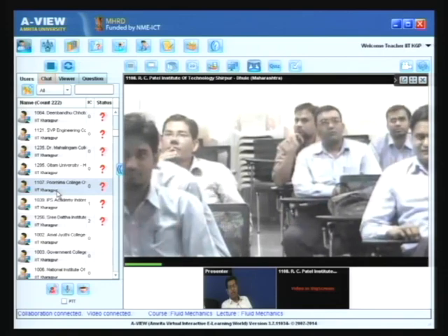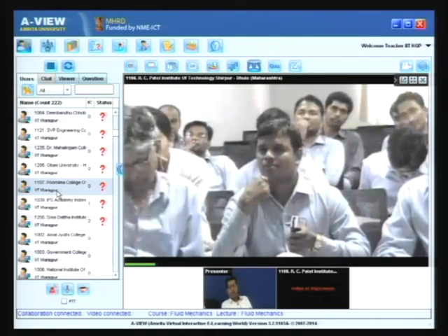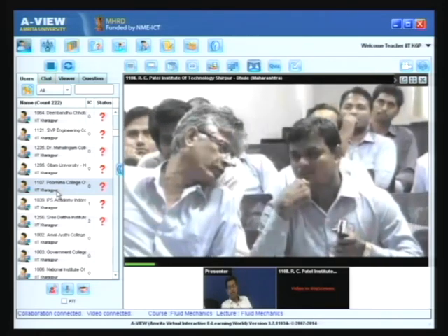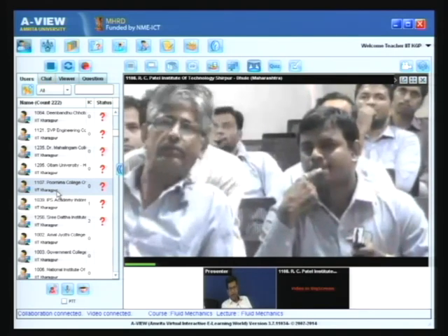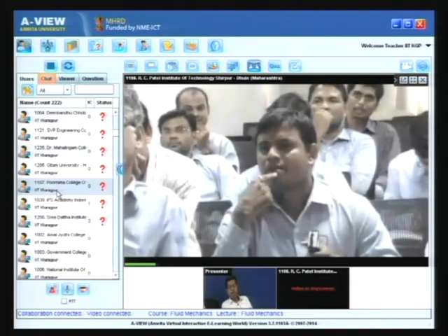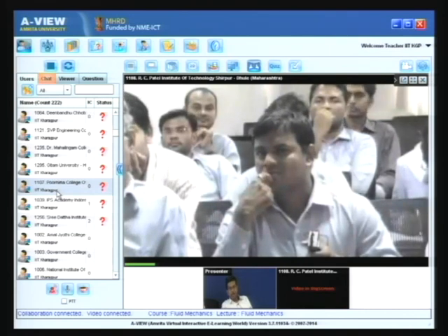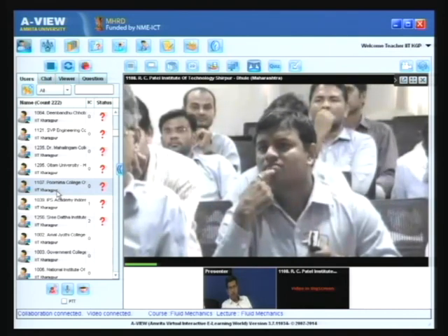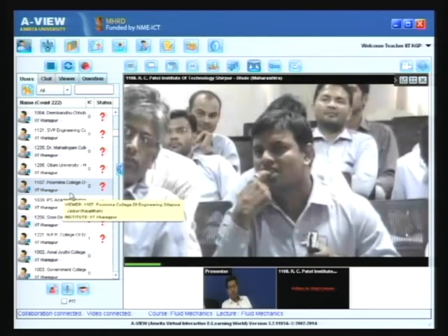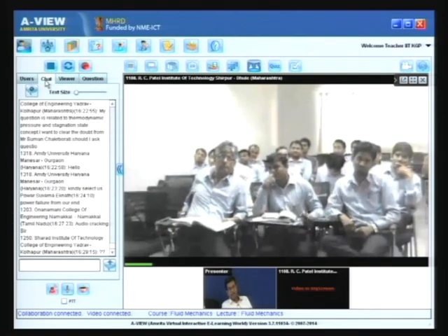In classical thermodynamics, the energy transfer between the system and the surroundings is classified into basically two forms. One is work transfer, another is heat transfer. They are two different entities. Heat is energy transferred because of the temperature gradient. Work transfer is of a different kind: viscous work, PdV work, shaft work. Shaft work is the work developed by the rotation of any device or system against an external resistance, known as shaft power.